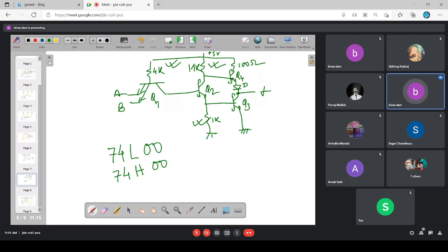Now, as I am improving the propagation delay by introducing Schottky transistors in place of the standard switching transistors, I can readily increase the resistance values so that the power dissipation inside the devices can be reduced. That means I am increasing the resistance values to reduce the power dissipation inside the device.